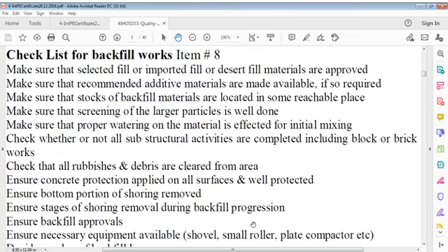you have to apply waterproofing membrane on surfaces, and protect that membrane. You have to provide something else, flexural sheet or whatever is specified in the method statement, so that when you backfill, your chips which go in the soil should not angularly touch the surface of columns or beams or whatsoever.